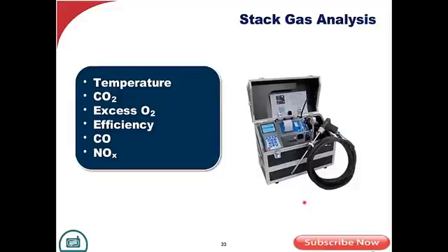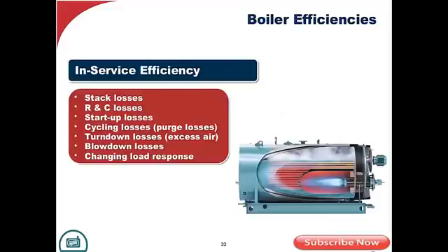So it's relatively simple, but by golly, when you go through an input-output and you compare it to the stack gas analysis, we're often very, very close. So I would rather lean toward expediency as opposed to something more complex when I'm looking at how I determine my overall efficiency.